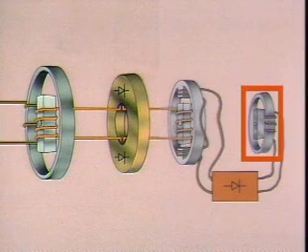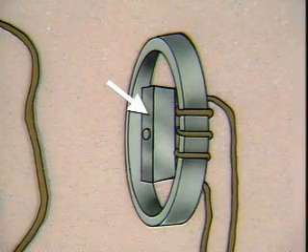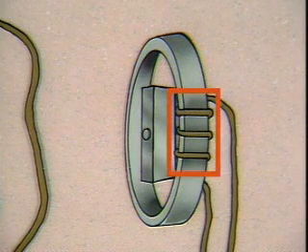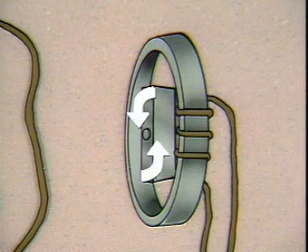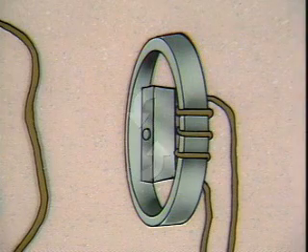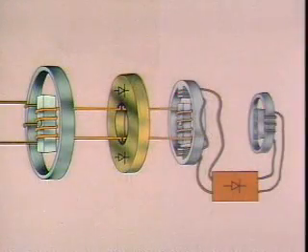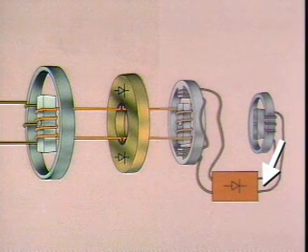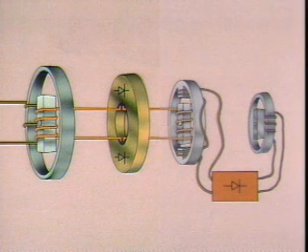This device is very similar to a pilot exciter, except that the rotor is a permanent magnet and voltage is induced in the stator windings rather than in the rotor windings. As the shaft turns the rotor of the permanent magnet generator, a small voltage is induced in the stator windings. This produces an alternating current that flows to the stationary rectifier bank. The rectifier converts the alternating current by dropping the negative half of the cycle.